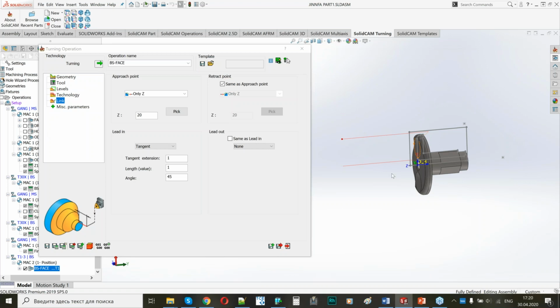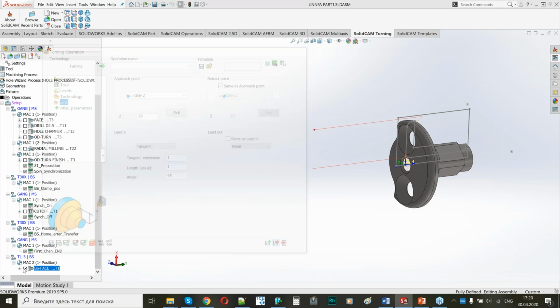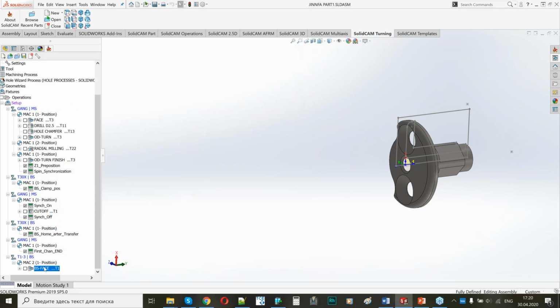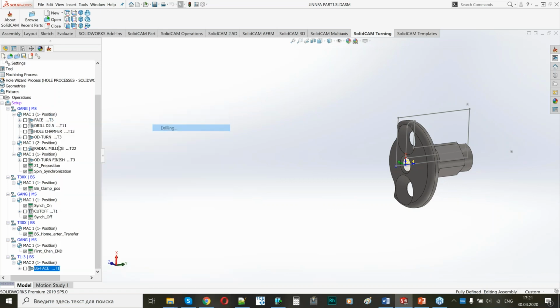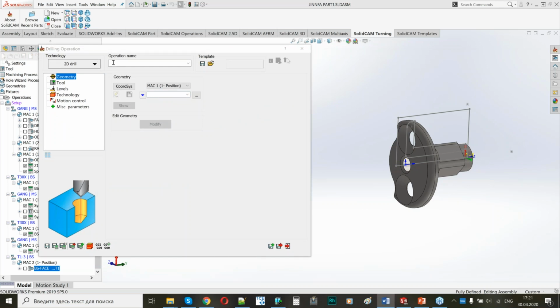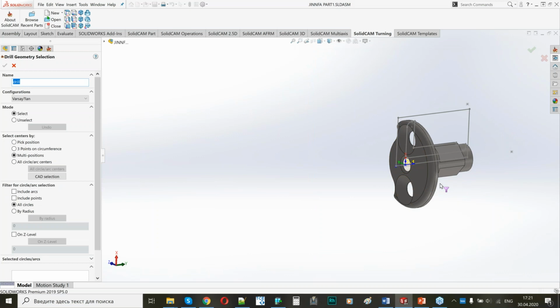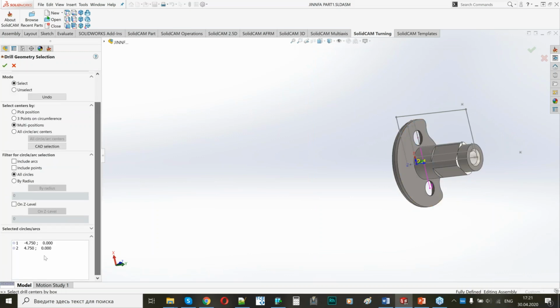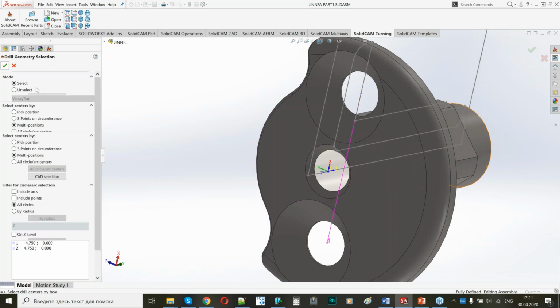Okay, what I need only drilling and some milling operation here. That's all I will add. So here I will have 2 milling drills. It's 2.7 diameter drills. I will choose my Mark II coordinate system again, and I will just click here, and I can see a list of my drills. It's okay for me.